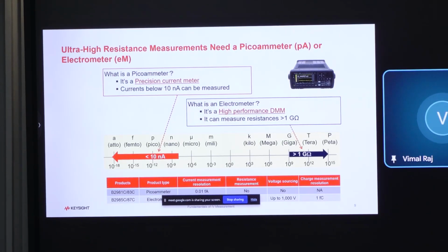So what the procedures are, we will discuss step by step. But at the same time, if you want to measure the resistance, you also want to follow it, because of the leakage. In the zone of high resistance, the current will be very low, in the nanoampere, picoampere range. Automatically saturation will be there, so the leakage will be reflected in the resistance also. Okay.